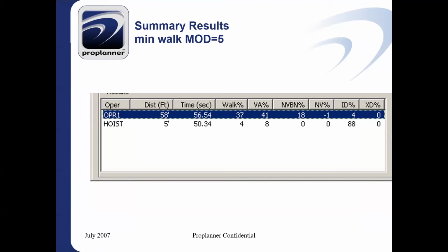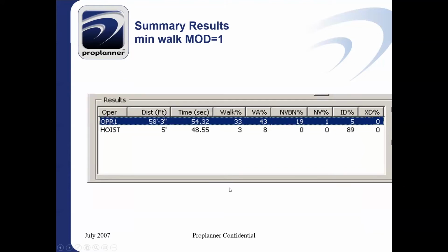And we have a classic man-machine problem where we may have multiple people working to keep that machine busy. External delay would be a situation where the operator cannot begin work or the operator may end work early and have to wait until their next cycle comes up before they could start work again. So external delay is time before they start or after they end, before their cycle can repeat. That would typically be a case where I have multiple operators and one of them has to wait for the other one to finish before they can do the cycle. So that's essentially what Workplace Planner is calculating.